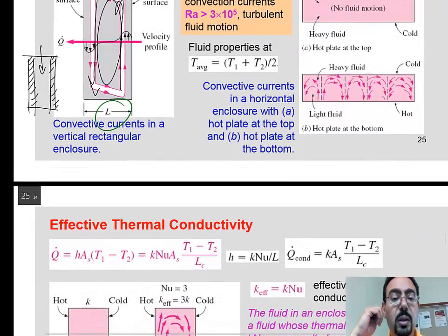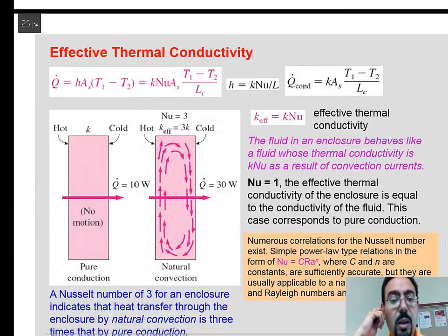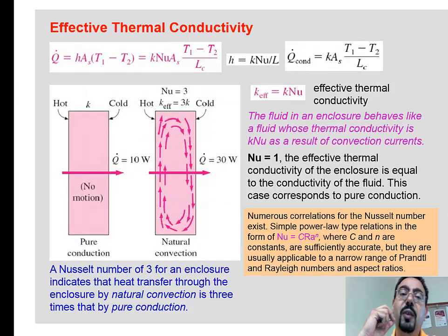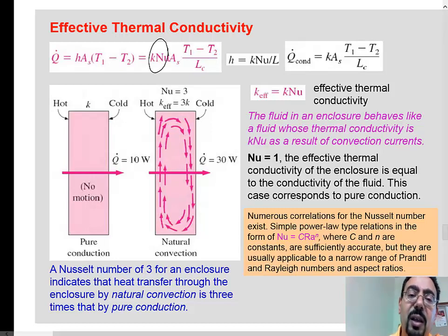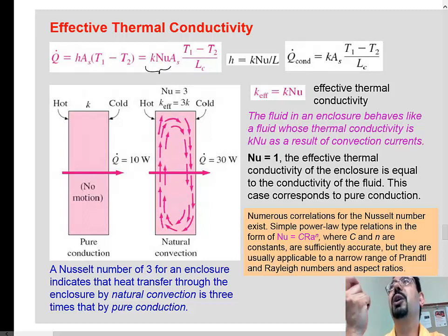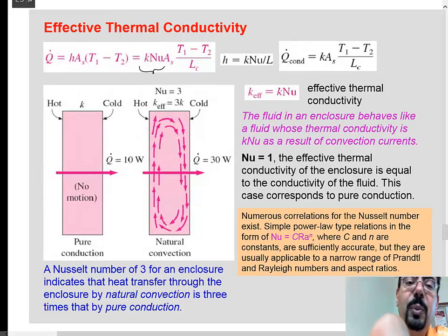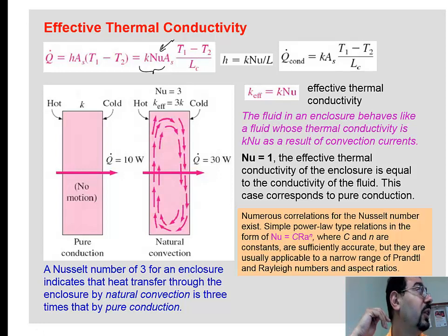All right. So we will not go through the calculation for this, but I just want you to know that this will result in eventually, as if you improved your K. That cell that starts moving, it will be as if you actually increased your K. So rather than having this K of nice small value, it gets a boost by the Nusselt number, generated because of the convection.